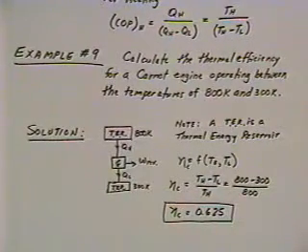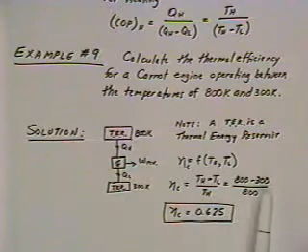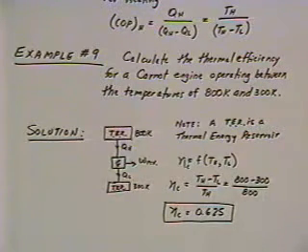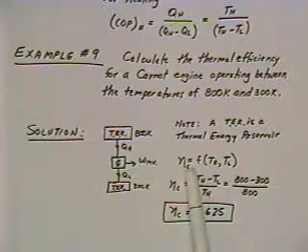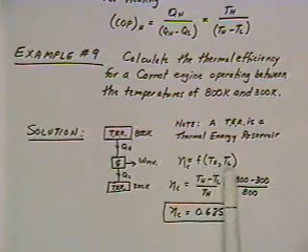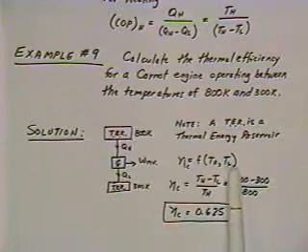So all you have to do is remember that you're using absolute temperatures here when you plug into the equations. I've made it easy for you by giving the problems in terms of absolute temperatures, but it could have been given in terms of degrees C or degrees F, and you'd have to do the conversions to get it into the absolute terms. Okay. Thermal efficiency of a Carnot cycle is just a function of the high temperature thermal energy reservoir and the low temperature thermal energy reservoir.